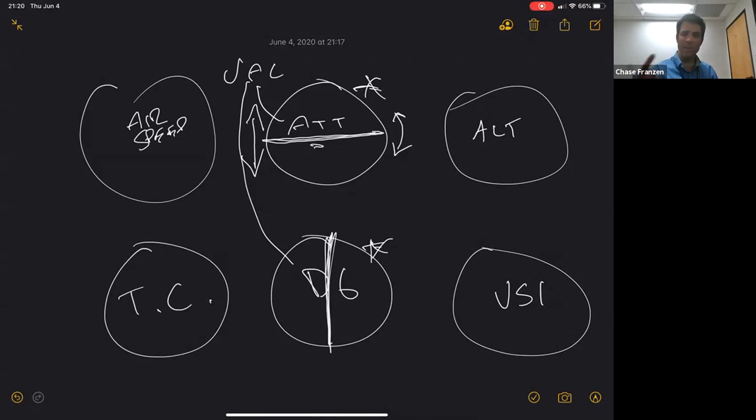Well, when you understand that there's this gyro inside of there, how else using the engine system alone are you going to spin this disc fast enough to really have it rigid in space? Well, you've got to come up with another system. So it's literally a little tiny motor creating suction, sucking air through it.